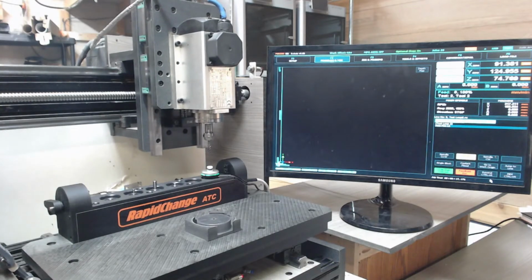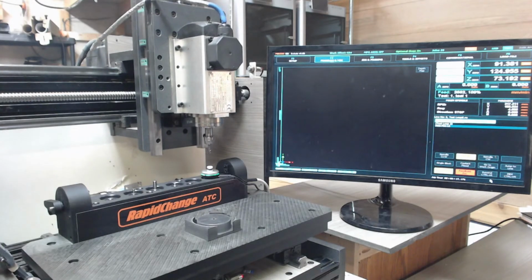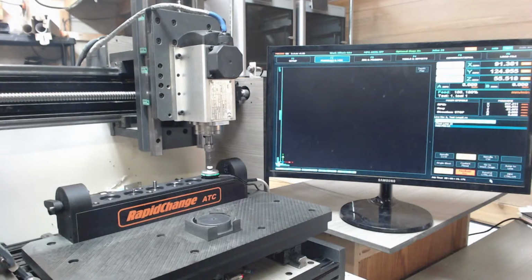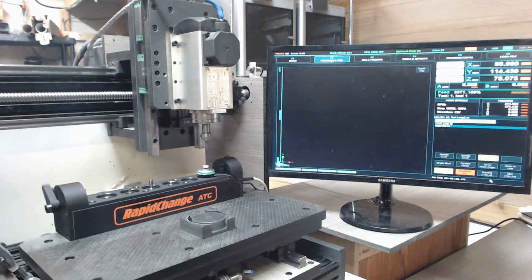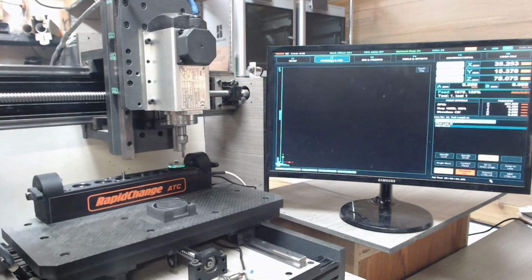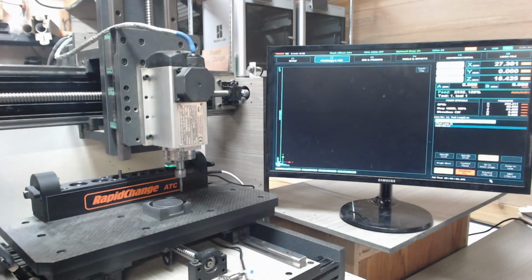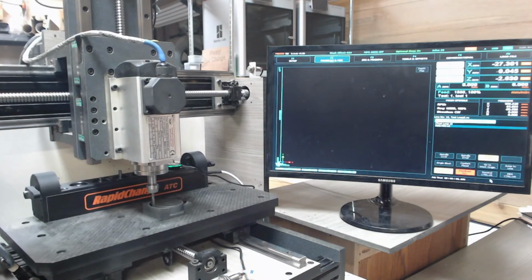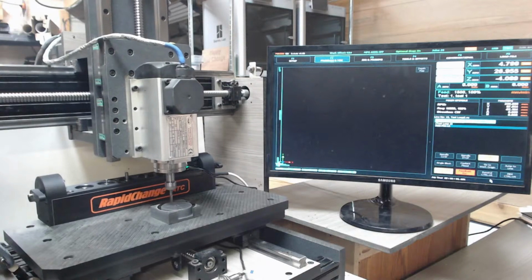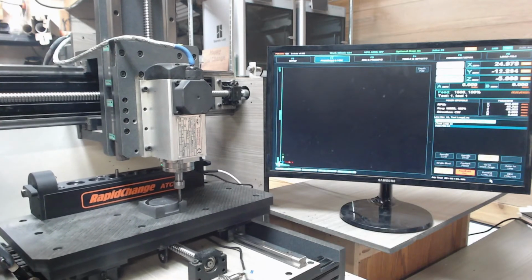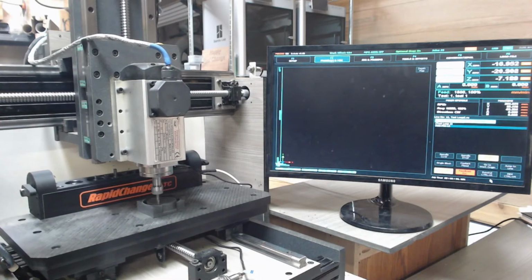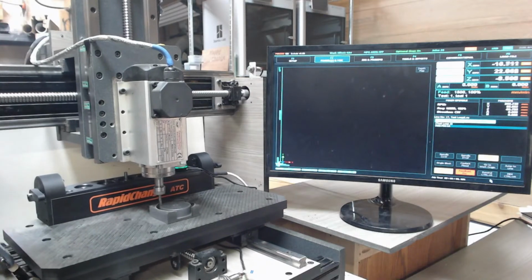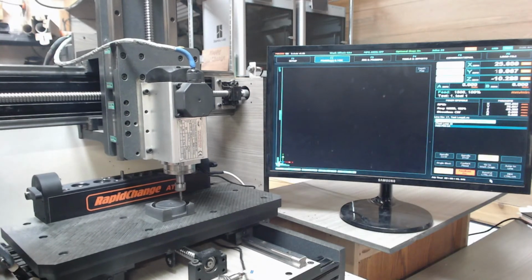Really, I was just looking for a pick and place rack, because I'm pretty disorganized and lose my tools and my wrenches all the time. But once I did get my spindle running in reverse and tried to drop it off at 1500 RPMs, it would get stuck every time. Well, it would work a few times and then get stuck, and then I'd change the geometry and it'd work and then get stuck again. It was a back and forth battle for months.